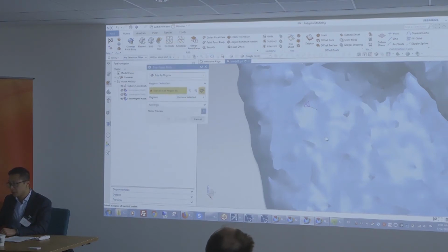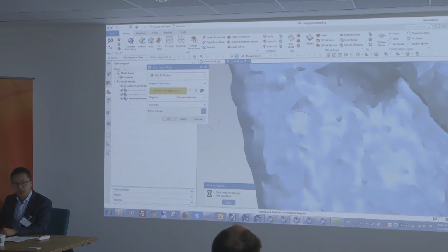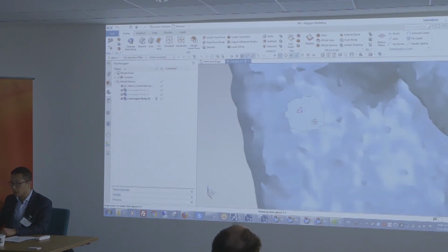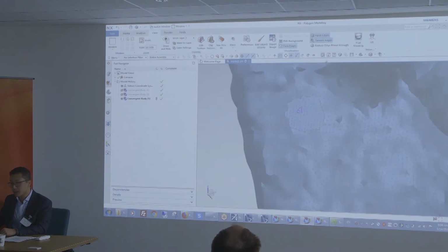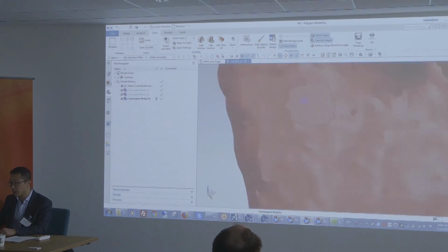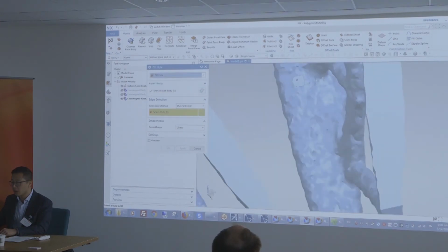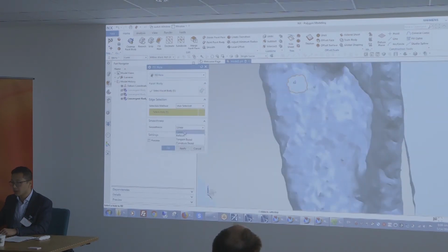look at the kind of things we can do, it's quite impressive. So I can use a brush, right? I can delete those face sets by just brushing over that area. So this creates a hole, right? So my geometry here is not a B-rep surface; it's a face set geometry. So it's full of face sets that we can play with. Now I can fill that hole by automatically detecting all the open holes in our body, just selecting it and closing it up.